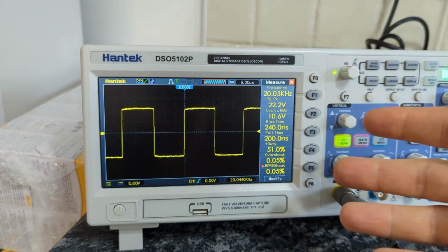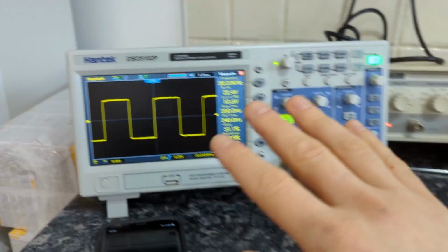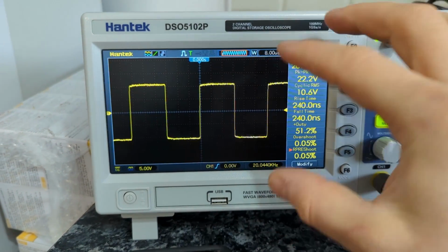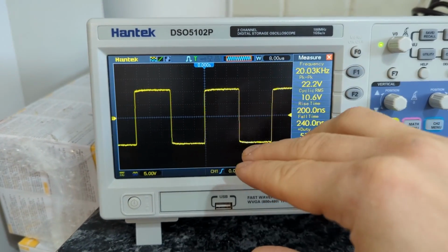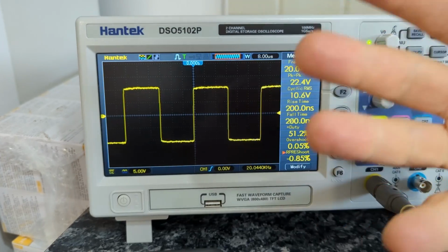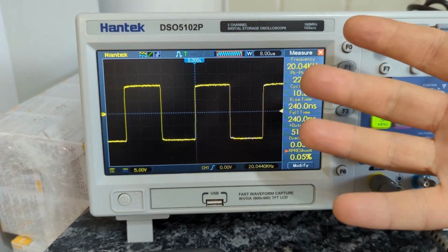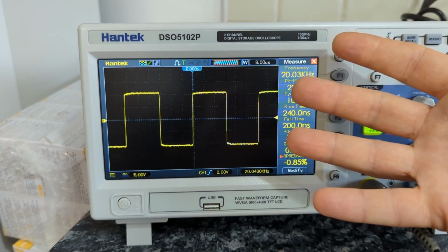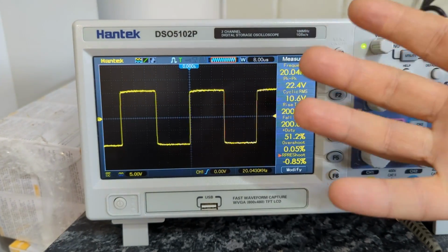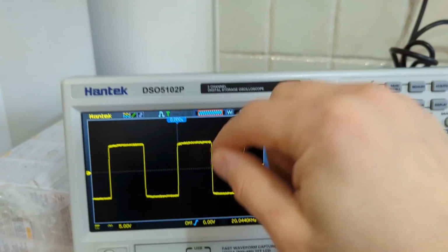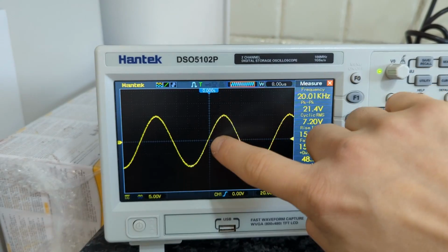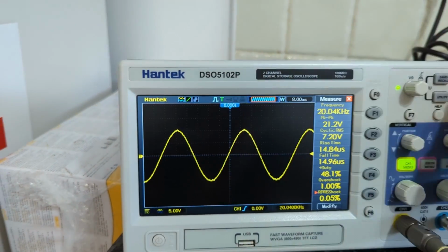And basically, if you feed this signal into the amplifier, it's not going to reproduce it 100% exactly the same because of the capacitance and everything in the amplifier, so it cannot. And depending on how well it reproduces the square wave, some people say that's where the quality of the amplifier comes from. That means that it can potentially respond faster to transients, to very high energy in music. So imagine you have a sine wave, but it's very high in amplitude, this edge becomes not that soft, but it becomes